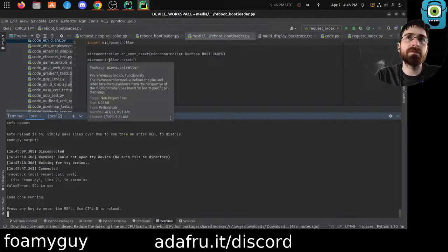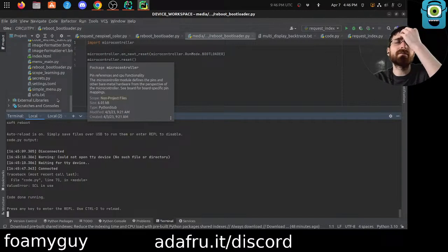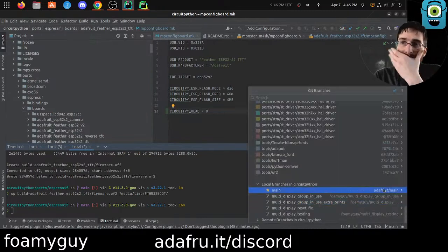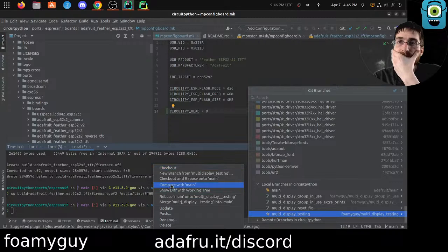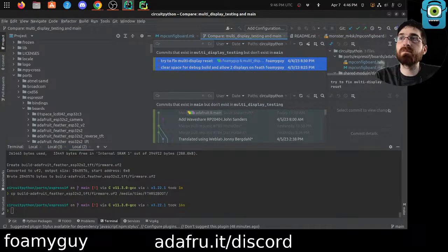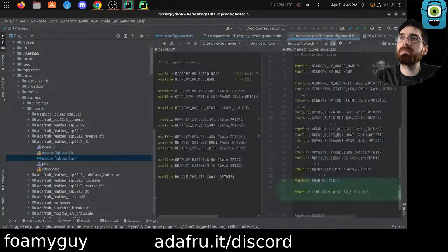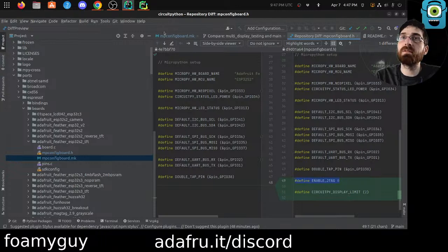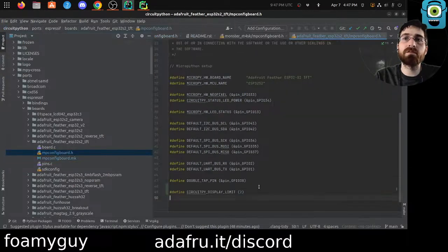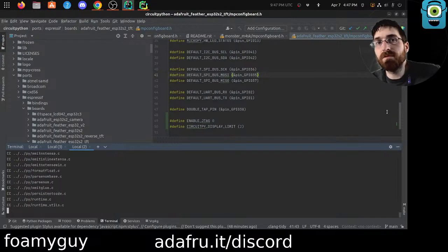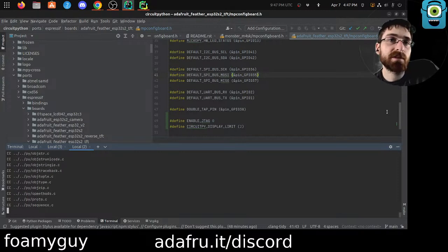SCL in use. Oh, yeah. Disable the something. We need to disable something else. That's weird. This JTAG. MP H. JTAG tries to use the I2C pins. But we don't want to do that, because we're trying to use the I2C pins to connect the display.